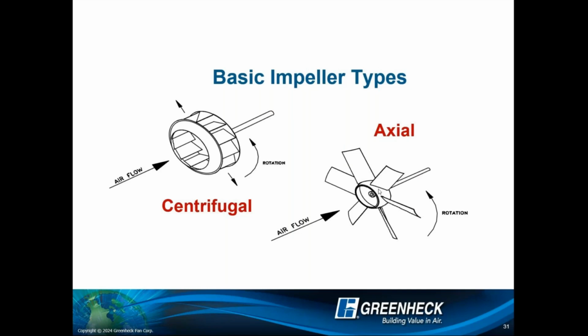If you think about a propeller, my rule of thumb is 1 inch of static pressure or less. Now, there are props out there, I know I make a few of them, that can handle 2.25 inches of static pressure. Yes, they are out there, but I'm just saying general rule of thumb, I stay under an inch.